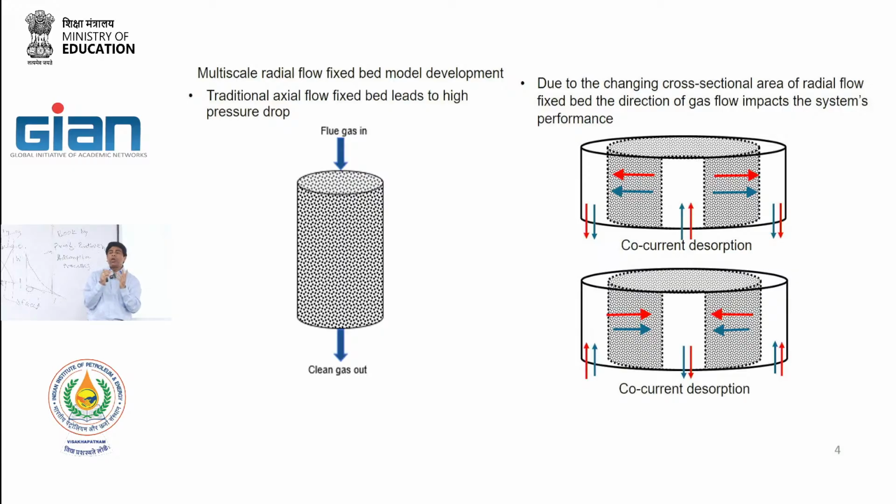If you simulate this bed, depending upon the annular size, it can speed up by 100 times, 1,000 times through that location. But it's a very short path length, and because of the very low residence time, it has no time to get recaptured. So many of these observations do not hold for the radial flow bed, okay?